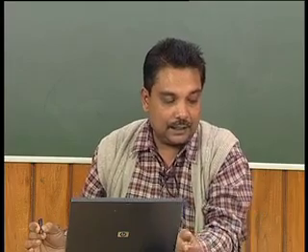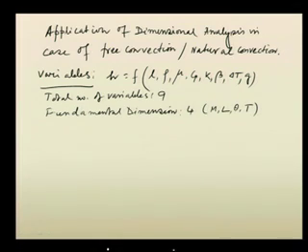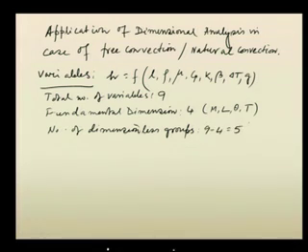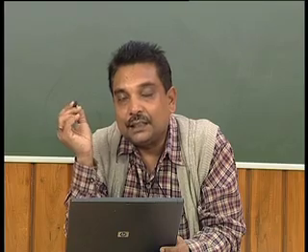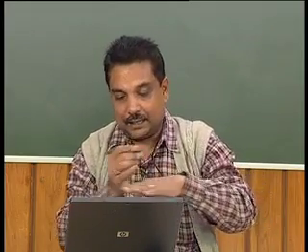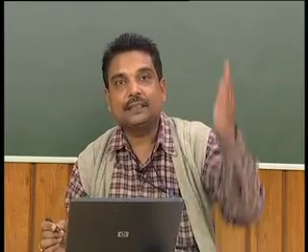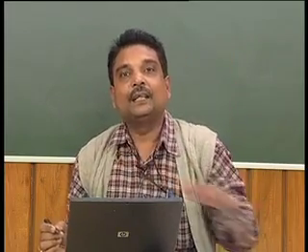Under that situation, the number of dimensionless groups that we may get is 9 minus 4, which is equal to 5, to define the system totally for a natural convection situation. Now, natural convection can take place over a hot plate. It can take place in a fluid adjacent to a vertical wall. It can happen to a fluid lying on a horizontal plate. In any of the situations, it can happen. Natural convection is very routine.